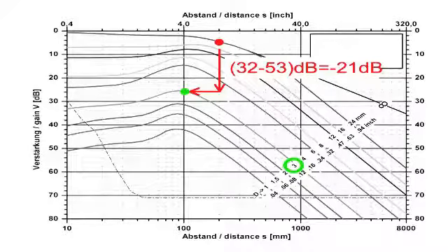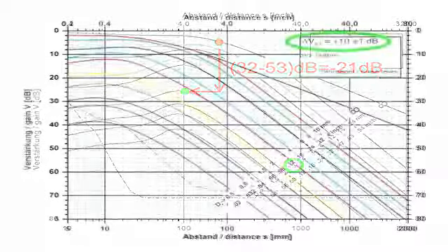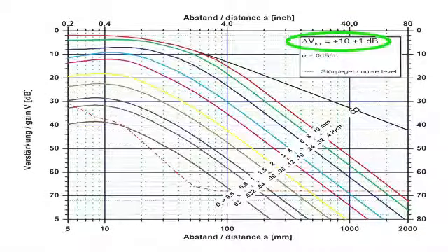When angle beam probes are used with the DGS method, normally there are no back walls available that are oriented perpendicularly to the sound beam. For this reason, one frequently uses the cylindrical surfaces of the standard reference blocks V1 and V2. Correction factors specific to each probe type are supplied on each DGS diagram that correct the differences between the signal from the cylindrical surface and the reference signal from a flat back wall at the same depth.